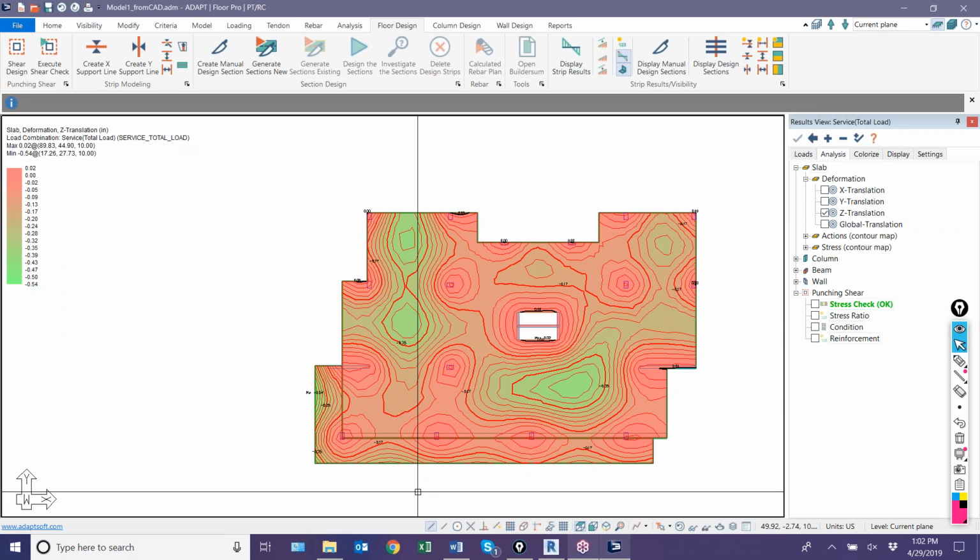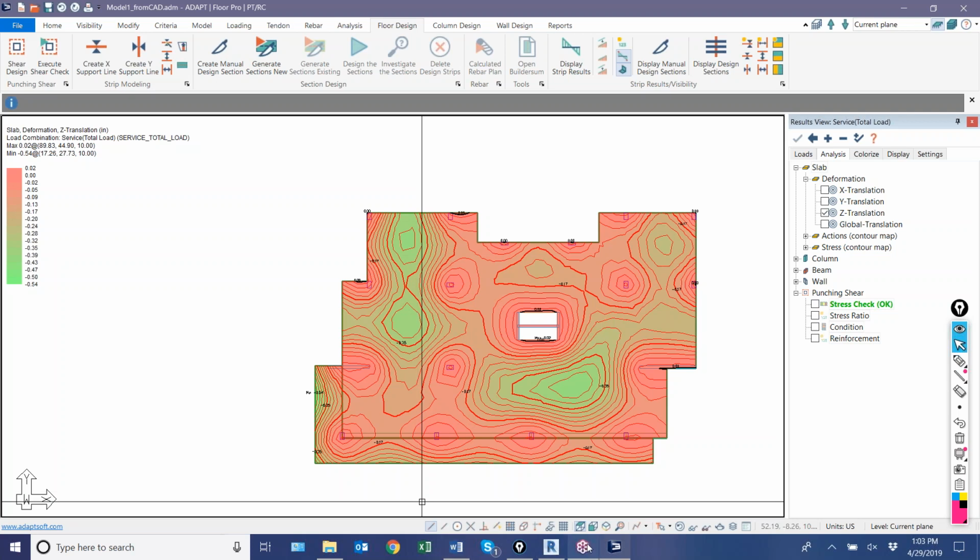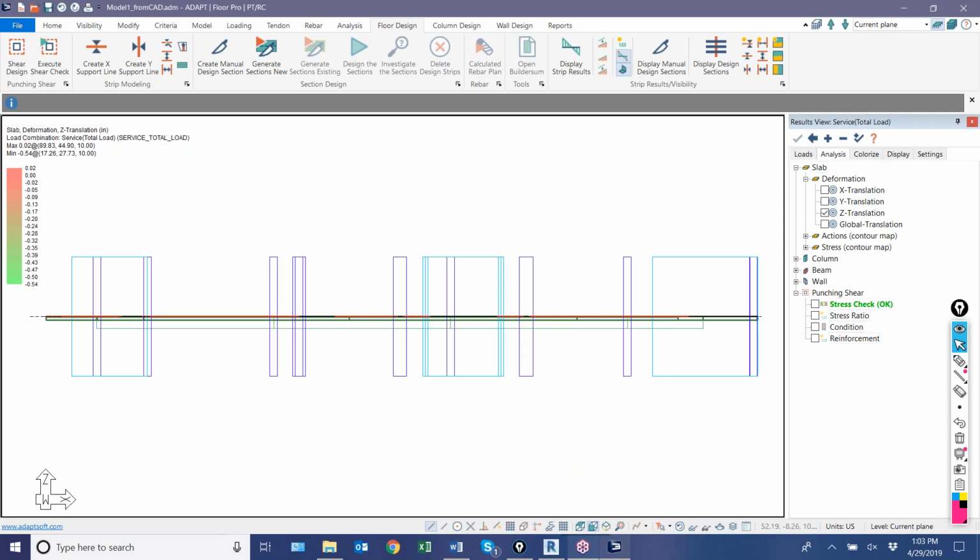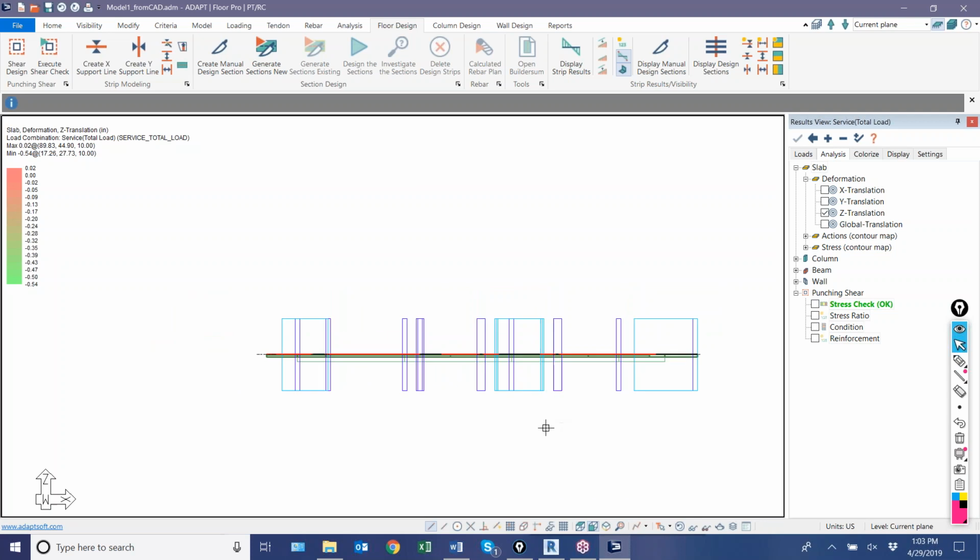Usually, when we check the initial stress conditions, it might be more appropriate to check with lower columns only. And then when we check the service total and the service sustained condition, we would check with maybe the upper columns. I think conservatively, you might use lower columns only for everything, but if you wanted to check different combination results per different settings, then what we would need to do really is